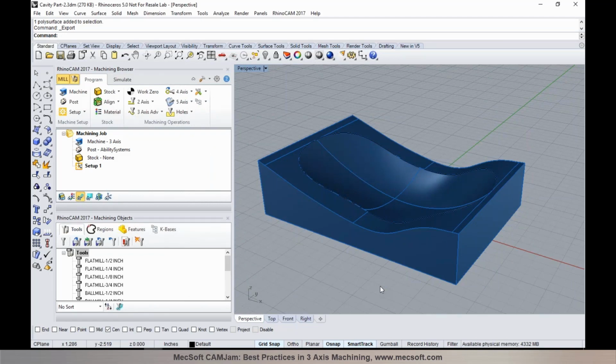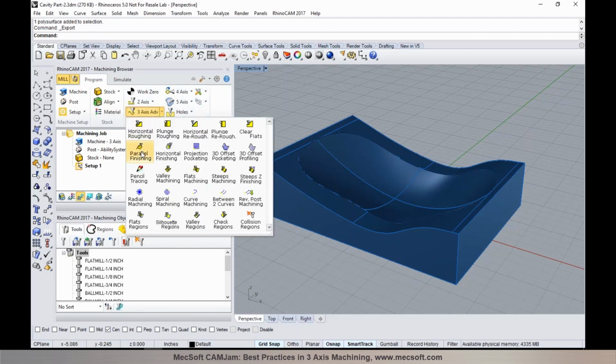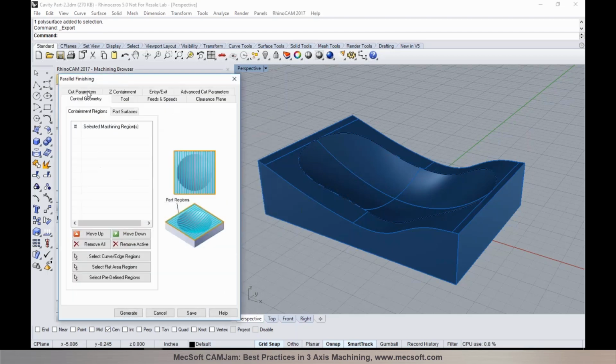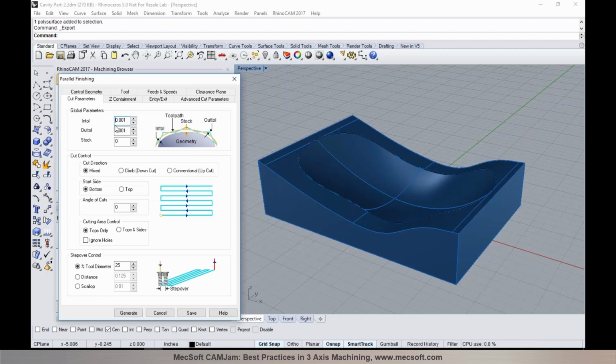So the importing of the CAD geometry, the CAD model facet information or facet tolerance, is not applied or not being used in Rhino and SolidWorks. So as you program or generate your toolpaths, the tolerance that you define in each of these operations is what controls the surface finish and the quality of the surface finish that you accomplish.